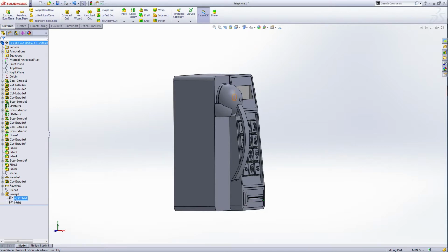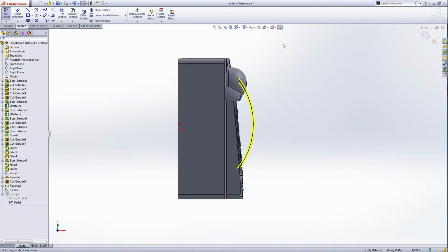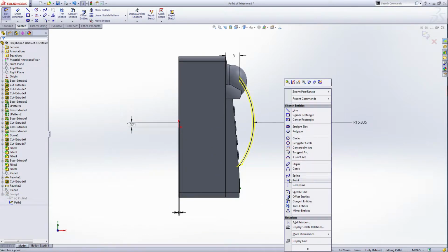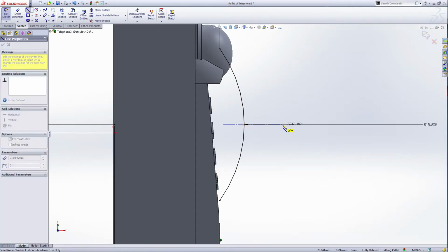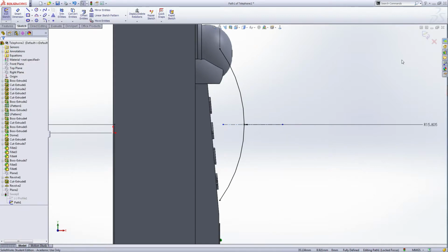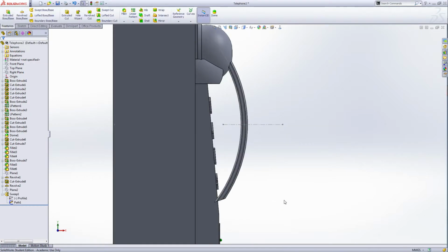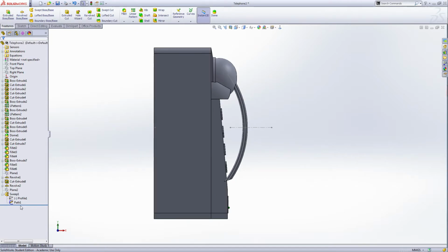So click here. Do you still remember the path we did? So show the path. We want to show the path, and the path we want to edit the sketch. So, normal to. First we'll add a point. So select a point feature and point on this line, and you can see the midpoint of this arc, click and then select. And now we can draw a center line like this. Okay, select, and this is the sketch. And now we show this path.